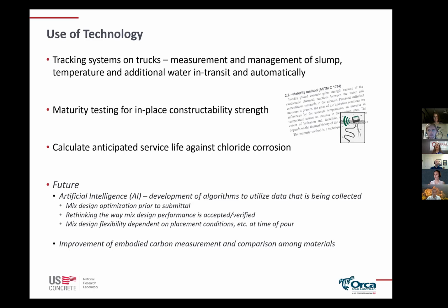So now we're at a point where there's a lot of data out there in terms of mix design strength and talking about the tracking systems on the trucks, and now trying to take that all together and use it to either do mix optimization prior to a submittal, or potentially rethinking the way in the future that performance is accepted or verified, or even allowed to adjust mix designs to do in-place conditions on the day of. So these are all things that we can be thinking about for the future, and ultimately to implement those will require cooperation between both the design community and material suppliers and contractors as well.